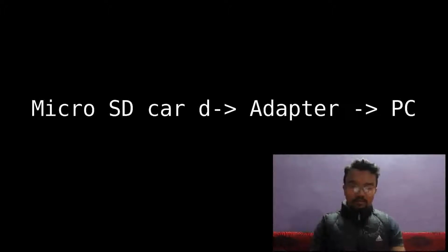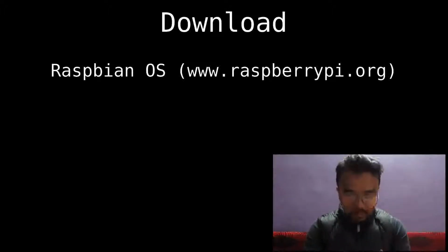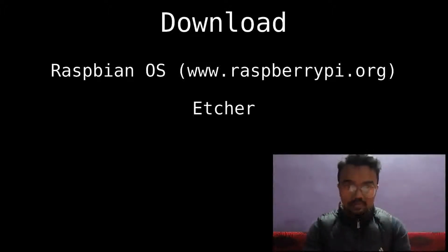Step 1. First, connect the micro SD card to the computer with the help of the SD card adapter. Then go to the website www.raspberrypi.org and search for the file Raspbian and download it. This will download the ISO image of the Raspbian operating system. Once the download is over, you will need to download another file, which is Etcher, on your computer.